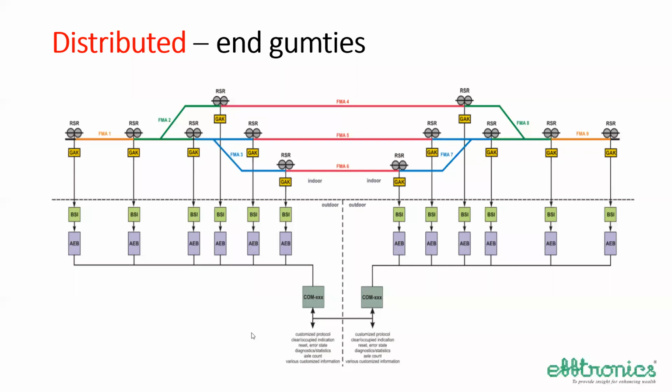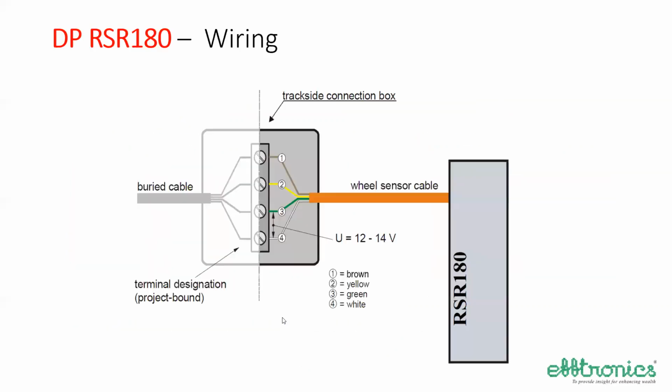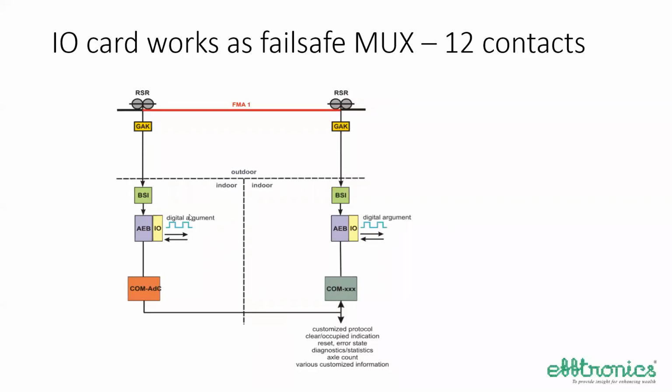Mr. Prashant Kumar has asked, is there any equipment that can provide both axle counter and block interface in a block section? These people have developed the same, but that is very costly and not introduced much. They have taken RDSO approval. This equipment is used for data exchange between the stations, basically. I told you, between the two IOs, 12 digital inputs are exchanged. For this application they have used it, not for axle counter. The axle counter anyhow has to be kept normally for MUX purpose.